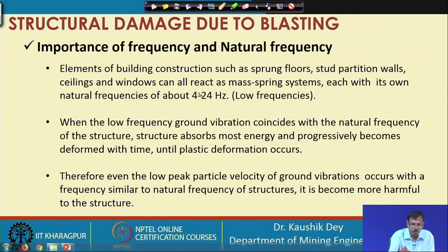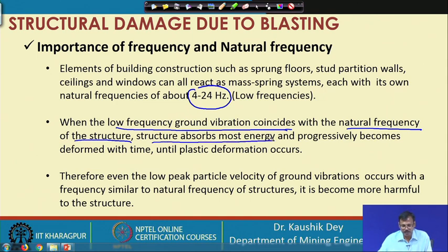It has been found that most of the civil structures have this type of natural frequency, which is low. Most of the cases blast vibration frequencies are more than this, and if low frequency ground vibrations coincide with the natural frequency of the structure, then the structure will absorb the maximum energy and it may deform progressively, and plastic deformation may occur. So, that is the resonance case, and that is why it is better to avoid this type of situation